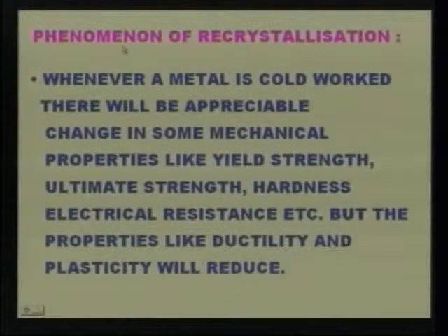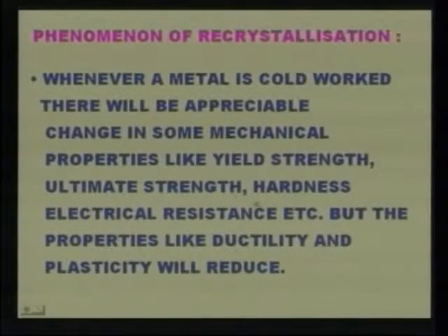Now let us see what the phenomenon of recrystallization is. Whenever a metal is cold worked, there will be appreciable change in some mechanical properties like yield strength, ultimate strength, hardness, electrical resistance, etc. But properties like ductility and plasticity will reduce.